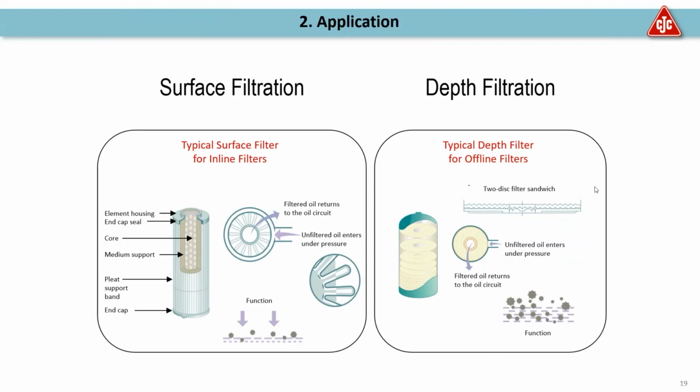What we do is depth filtration. They're basically very dense cellulose-based filter inserts that filter through a very deep filter, and they hold anywhere between 100 or 200 times more particles than a typical surface type filter. The added benefit of this depth filter is also that it absorbs water. And in the size for your ACC fan gears, it'll be a half a quart of water that it can absorb and about 2 pounds of dirt.